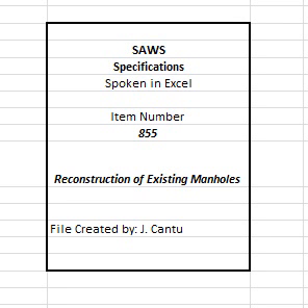6. Throat rings shall be made of HDPE and have a maximum thickness of 2 inches. A. The internal diameter shall match that of the ring and cover opening. HDPE throat rings are to be used in conjunction with a UV-stabilized internal polyethylene liner for the purpose of providing an infiltration/inflow, I/I, barrier. Concrete rings are not allowed.